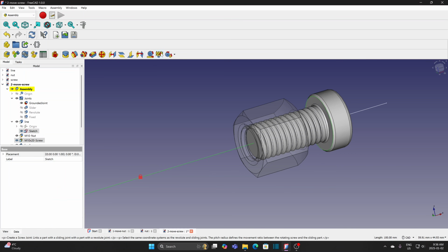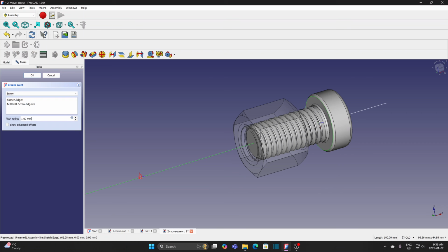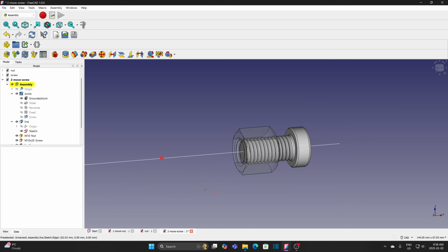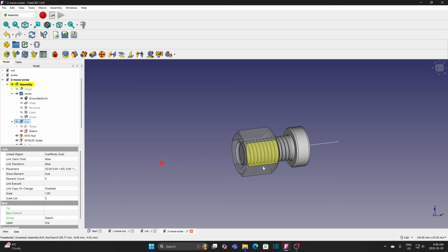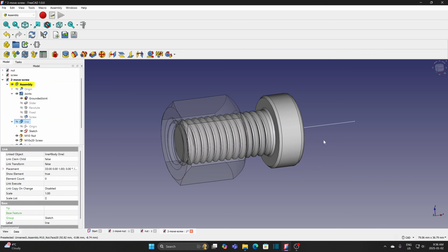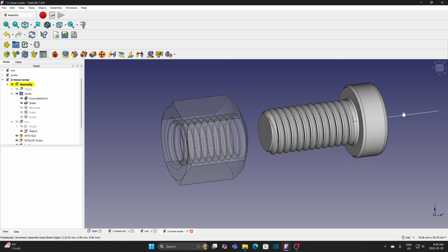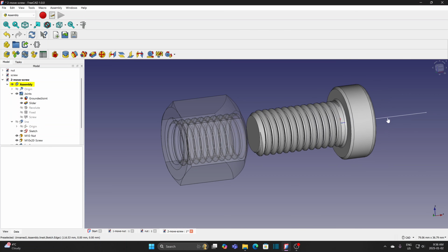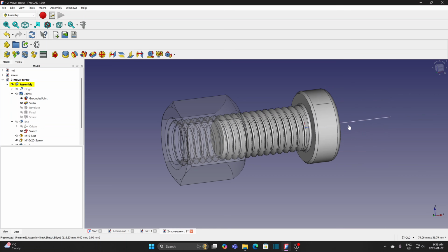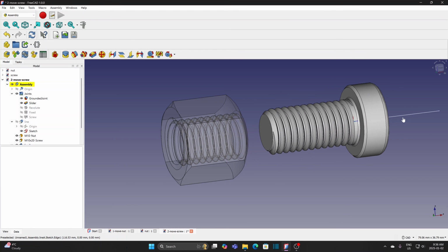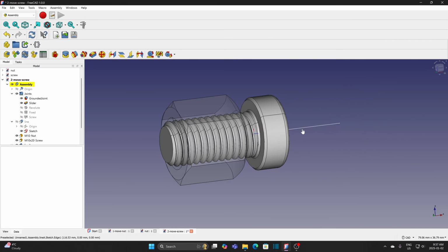Create screw joint. The pitch radius is in fact the pitch of the screw. With M10 screw, the pitch is 1.5 mm. Hide the long line. Drag the short line to move the screw. When the screw moves forward, it rotates clockwise. The rotation direction is correct. With the same approach, I will create a vise assembly and use screw joint to move the jaw but without using a supporting line.